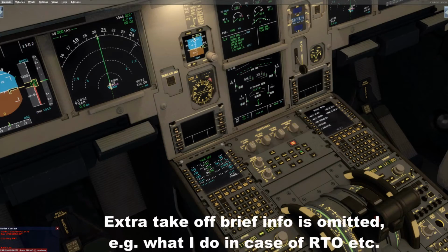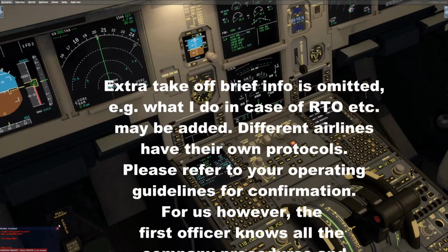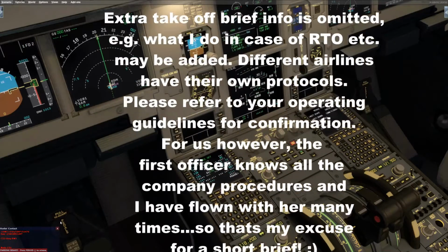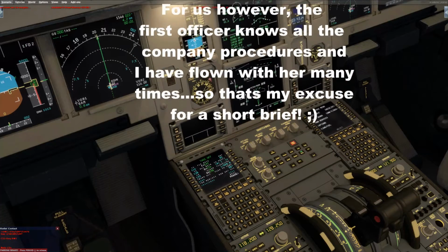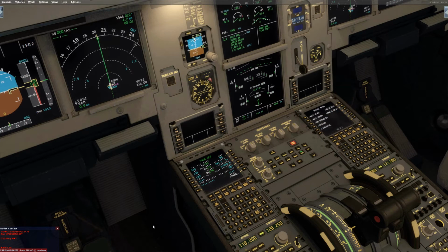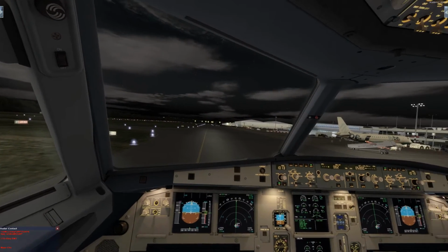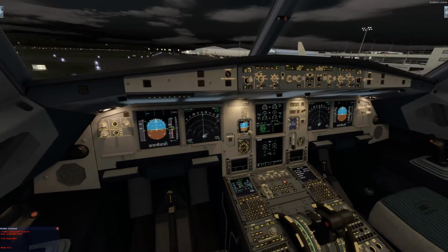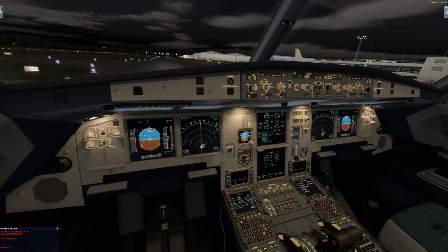Okay, takeoff briefing. We'll take off and fly runway heading. Climb to 400 feet. At 400 feet, engage autopilot. We'll monitor the autopilot and fly the SID out to Goodwood and Midhurst. Thanks. You're welcome. Okay, ground service is clear. Taxiing to runway 02. You can give Jessica the nod for her Airbus taxi brief now.